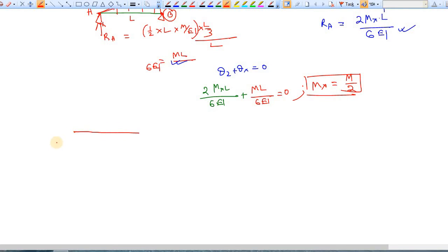Let's say this is a beam, it has a support here pinned, and this is also pinned. Now the rotational stiffness is calculated based on the moment required at this point. This is the pinned or simply supported point for unit rotation. If we apply moment, it will rotate. So to produce this unit rotation, how much moment is required? That is the rotational stiffness of your beam. Now let's find for different far away conditions. It may be pinned, it may be fixed like this. What is the rotational stiffness?